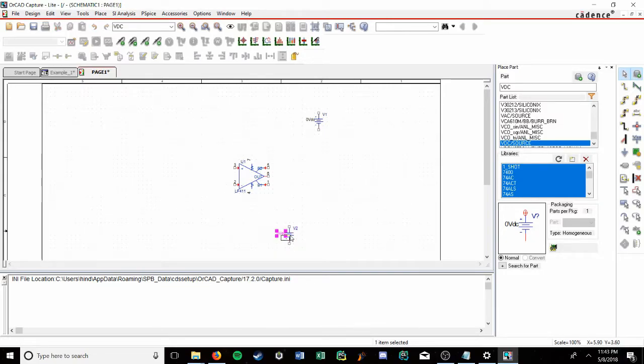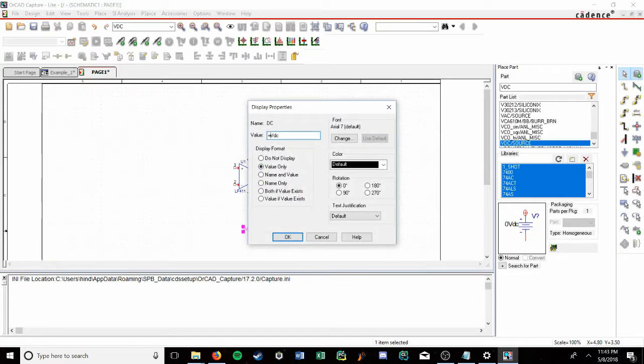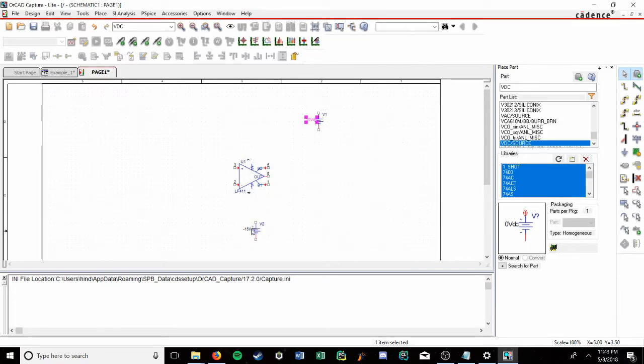You can drag an element if you hold and click on it, and put it where you want. So if I want to line it up, you can do that. With the first one, you'll want to use negative 15 volts. And with the top one, you'll want to use 15 volts, which is going into pin 7. And the negative one is going into pin 4. And now, just a quick tip, you want to close off these 2 pins, pin 1 and pin 5, because we're not using them.